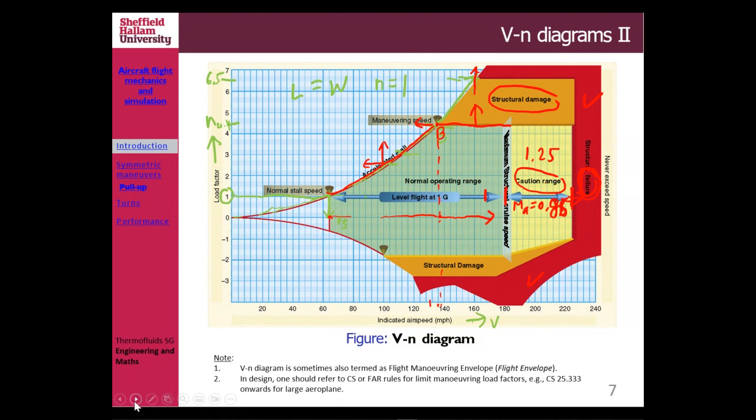Okay, right. So I hope that gives you some idea. As I said, as an aircraft designer, you must be able to draw this flight envelope for your aircraft with all the information about your aircraft weight, for example, your stall speed, your CL max. Now, in terms of the maximum load factors, we refer to CS25, but of course, there are minimum load factors that you could also consider here.